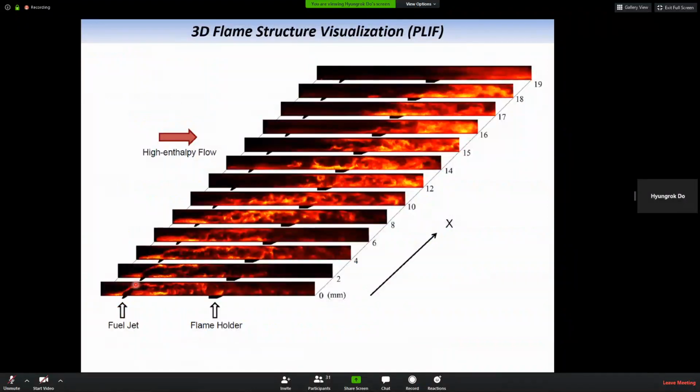But when you inject the jet, that is producing a strong shock wave, and the shock wave will increase the temperature and pressure behind. So by the shock wave, a strong combustion reaction is occurring here. And in the downstream region, it will be well mixed with the incoming air and the fuel that are now circulating behind and mixed with the incoming air. And then the combustion reaction is occurring in the downstream region.